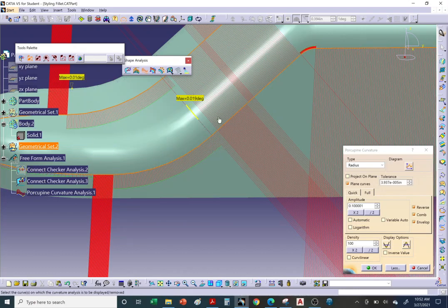So this is telling me that as you transition from here to here, it's tangent. We're trying to avoid tangent continuity. We're trying to get curvature continuity. If this would have been curvature continuous, this green line would have curved and then lined up with the linear surface, or I should say straight surface, the cylindrical area. So we would actually want this green line to curve as it goes, if it continues on. Here it breaks and continues on elsewhere.